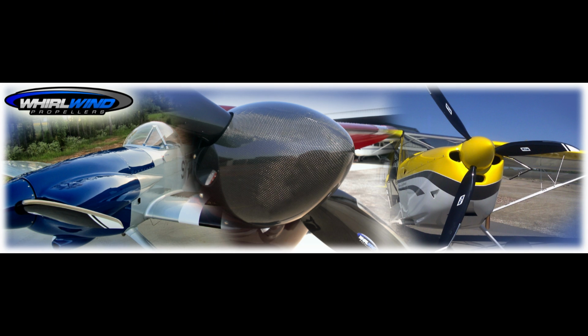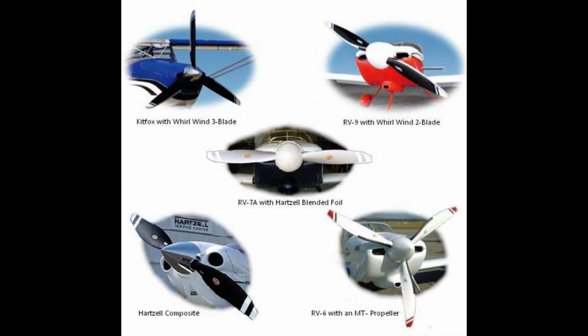Ground adjustable pitch propeller. Adjustable pitch propellers for WSC aircraft can be adjusted only on the ground with hand tools. If an engine is over revving, more pitch can be added to the propeller. If the engine is not developing the full recommended RPM during flight, then some pitch can be taken out of the blades. This should be done according to the WSC aircraft's POH and by a qualified technician.